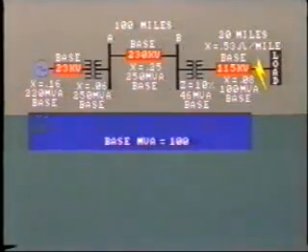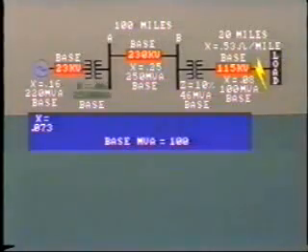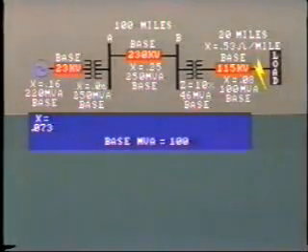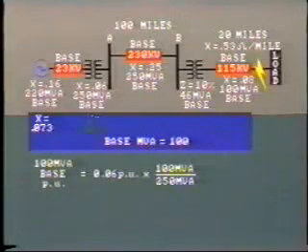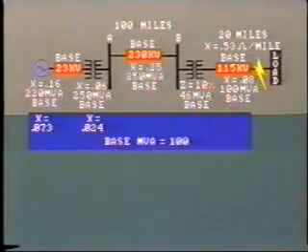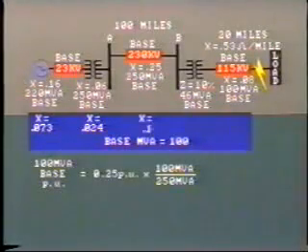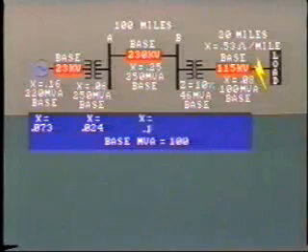Mark this on the diagram. Similarly, the step-up transformer reactance, 6%, must be reduced from 250 MVA to 100 MVA base. This gives us 0.024 per unit reactance. The 230 kV transmission line indicates per unit reactance of 0.25 on a 250 MVA base. This converts to 0.1 on the 100 MVA base.